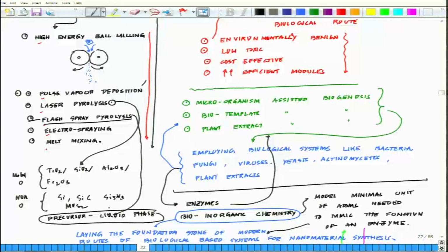The important technological element of this process include self sustaining flame, usage of liquid feeds and less volatile precursor, and it has very high scalability, high temperature flame and large temperature gradients. So, these are some of the techniques, some of the prerequisites for flame spray pyrolysis.